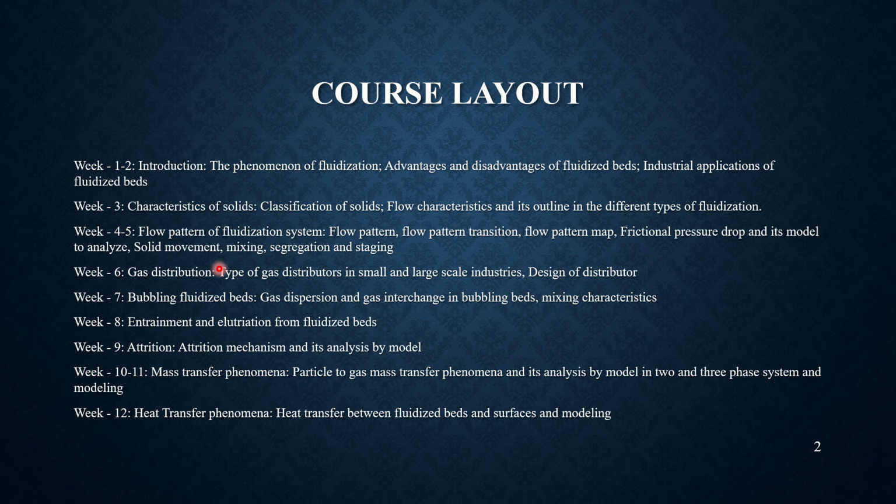What are the heat transfer mechanisms taking place inside the fluidized beds and the surfaces, and the modeling for the same, and the design of the fluidized bed reactor for physical operation. See, it is not only about physical operation, but we are also dealing with catalytic reactions and non-catalytic systems. So depending on the purpose, it is required to design the system accordingly. So unit operations, unit processes, all those we have dealt with in chemical engineering.